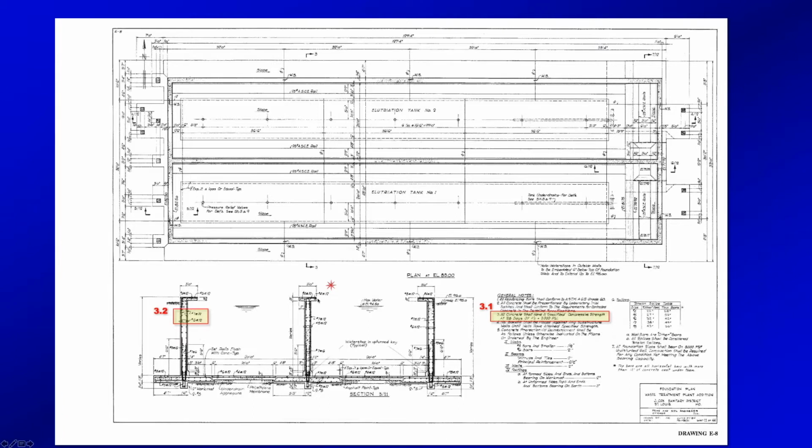Okay, so someone could ask you what's the distance from here and the opening from to there. And if they don't give it to you anywhere, how would you figure that out? The answer for 3.2, when it's asking the bar size and spacing of the outside walls, where I know you have it highlighted under your 3.2, but how are you knowing that that's the area?